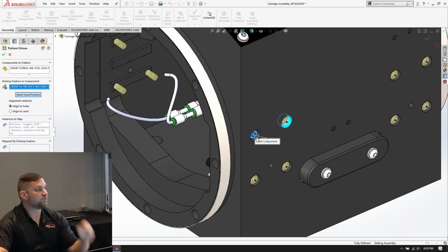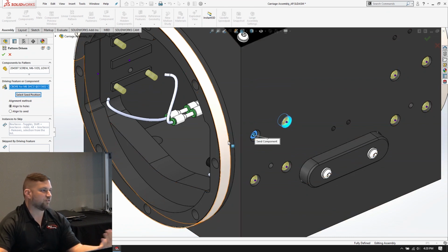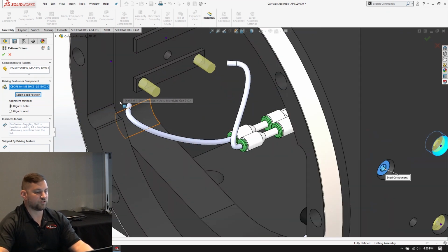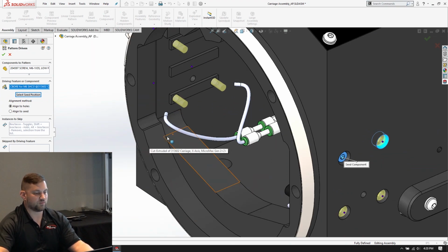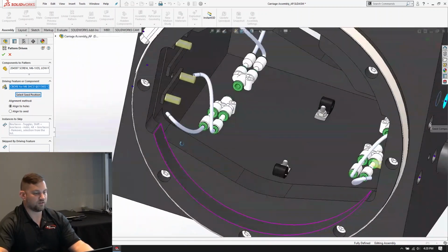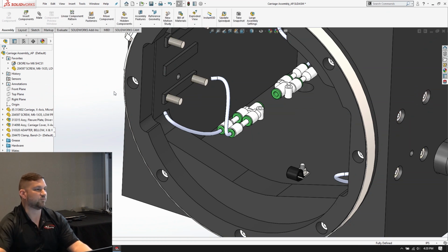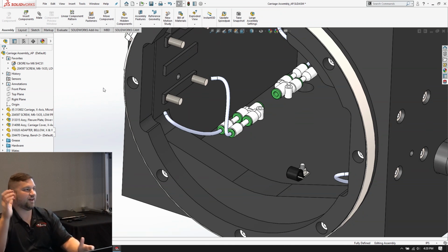Now, instead of screws floating out here, I want to select my seed position, which is exactly where this screw is. But what's brand new for 2020, because all that you could do prior to 2020, is that you're going to notice it understands the direction of Hole Wizard holes. So you see the screws back here, these previews, they are in the socket head cap screw hole in the appropriate direction. So align to seed is the old way, and in 2020 I can now align to holes, hit my green check mark, and I don't have to do it a couple times. Super efficient. Super awesome.